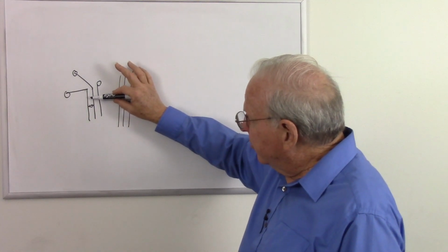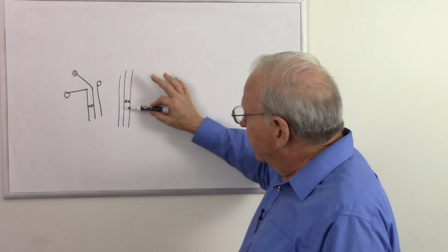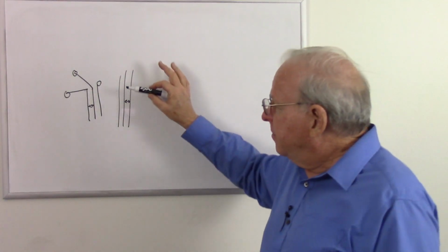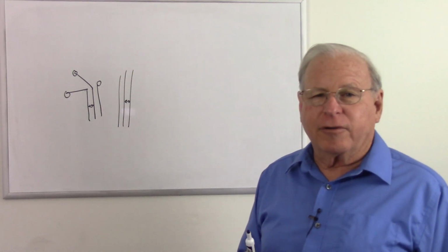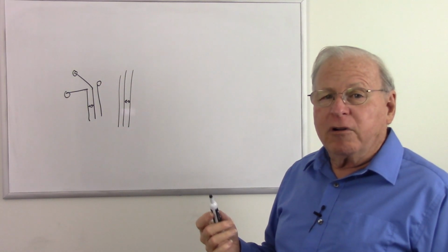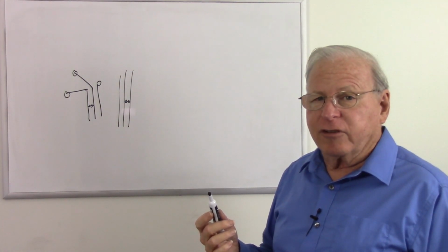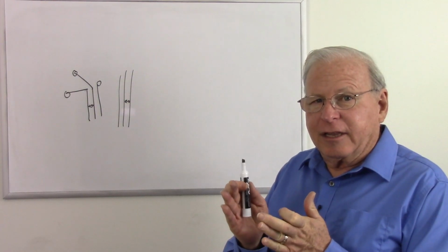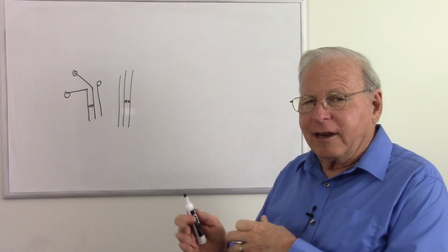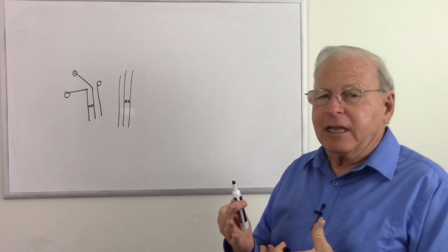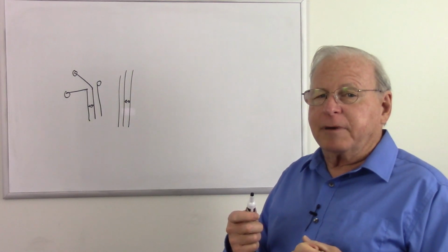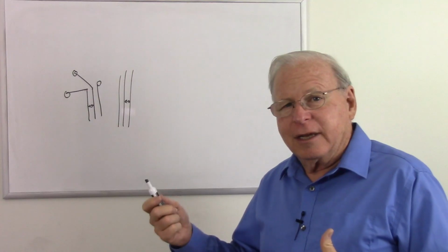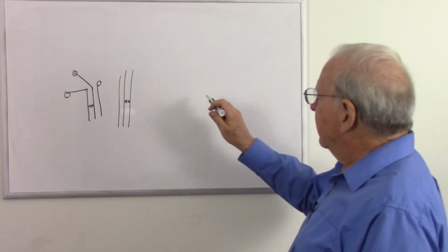So parasitic capacitance is capacitance that exists where we don't design it, but just because of the nature of what a capacitor is, we get capacitance. Components have parasitic capacitance. A transistor or a diode has a junction, and there's conducting area, insulated area, conducting area. We expect it to be non-conducting across that junction, but because there is capacitance, we get some conducting through there.